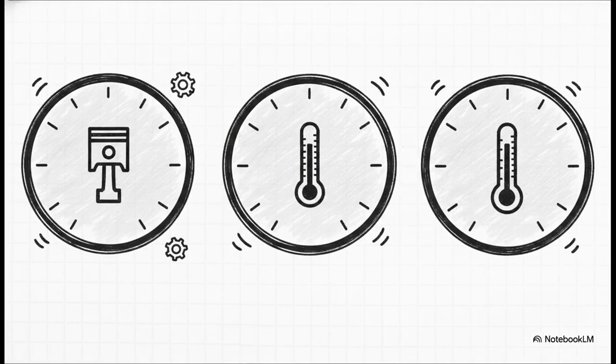For these conventional 500 megawatt baselines, we're typically looking at a main steam pressure of 170 kilograms per square centimeter. The main steam temperature sits at about 537 degrees Celsius, and the reheat steam temperature is pushed just a bit higher to 565 degrees. For decades, this was the absolute workhorse of the industry. But given those macro challenges and the techno-economic realities we just talked about, honestly, this baseline just isn't going to cut it anymore if you want to future-proof your investments.